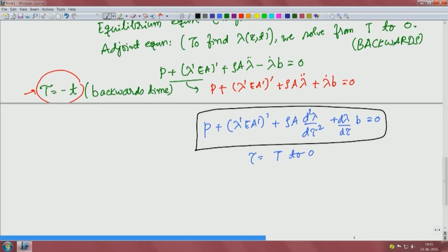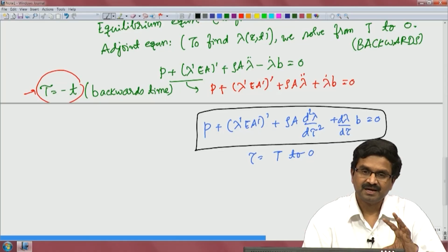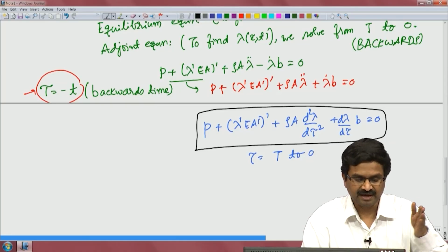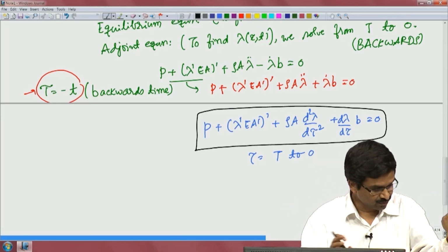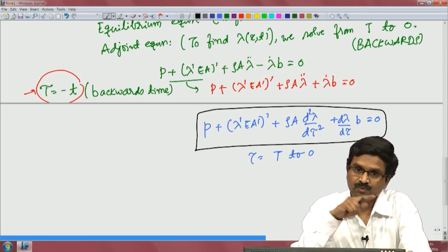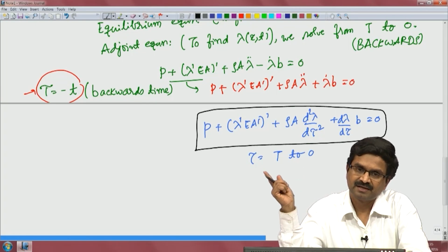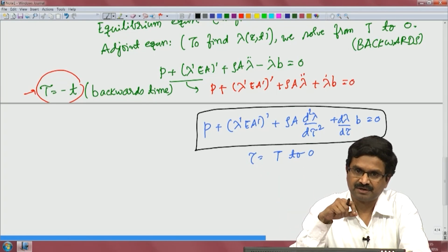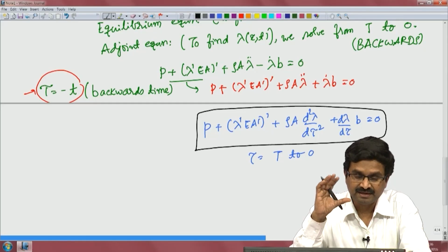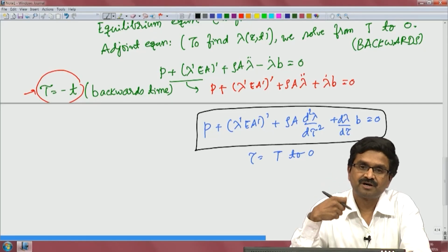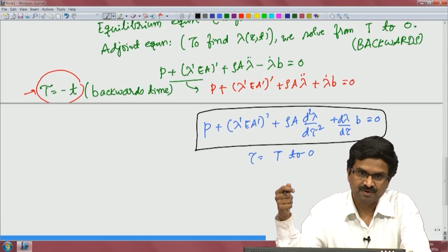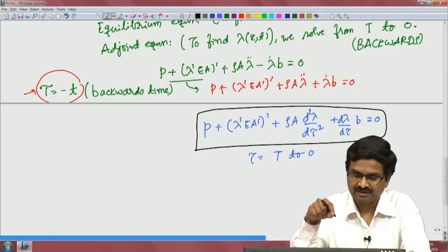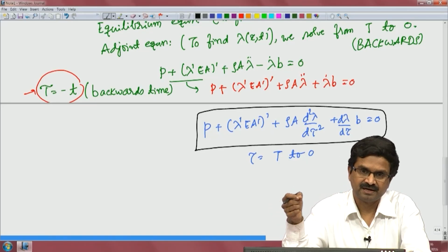So, for us to solve, we can use the same finite element routine to solve it rather than going backwards in time. Okay. This is what happens when there is a sequential time equal to 0 happens, 1 second, 2 seconds, whatever 2.5 seconds. When it goes like this, we go forward for equilibrium equation and then come backwards in negative time for adjoint. This is the characteristic of the adjoint method when there are these first order terms there. This can also happen in sequentially coupled multiphysics problems, which we will see after this into the next half of the lecture. Thank you.